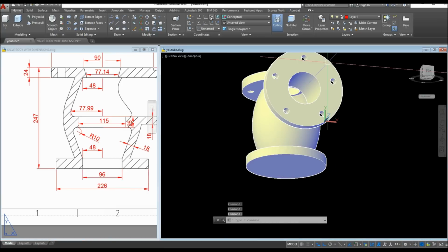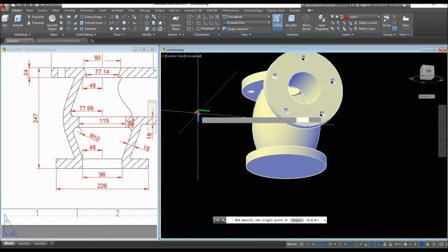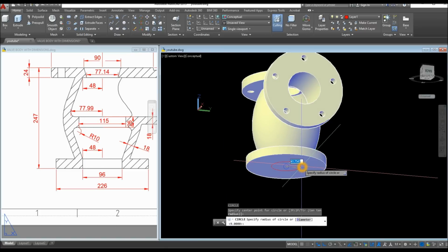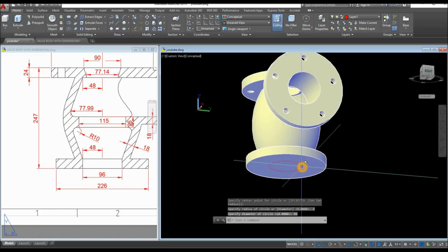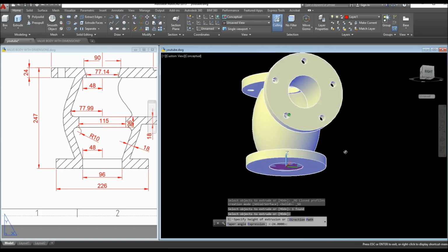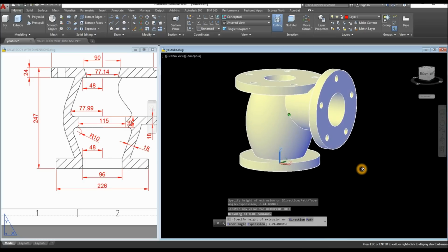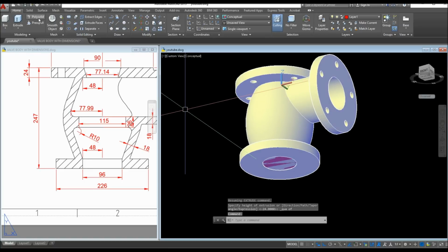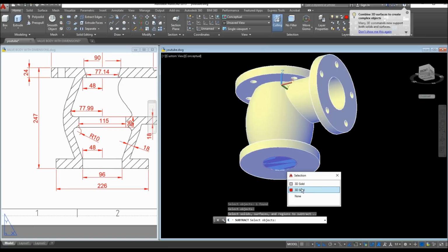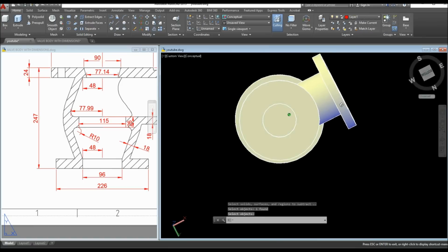So C for circle, I'm gonna change again direction of the UCS. So Z-axis vector, point it upward. C for circle, snap that center, type D for diameter option and enter 96. And I'm just gonna extrude this one up to a quadrant somewhere here or up to a center here. Oh, just quadrant there, and subtract, select that and select this object. And I think we're done.